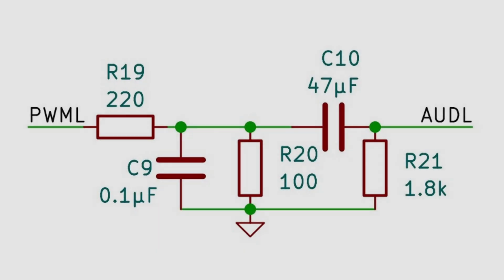Some of you engineers will remember that a square wave is the sum of a series of sine waves. That means we can apply filters or use other techniques to turn these square waves into something else. The Pico computer uses a simple filter to turn high-frequency square waves into an analog signal. And now you know why PWM is sometimes used: price.